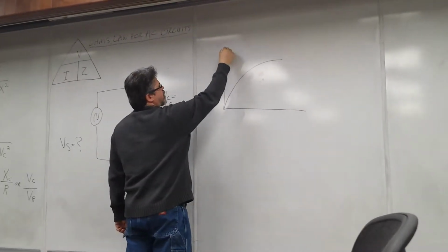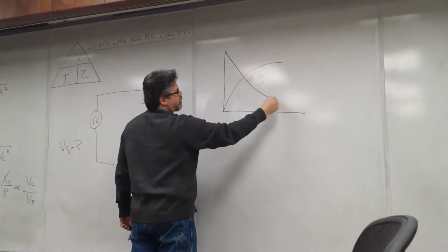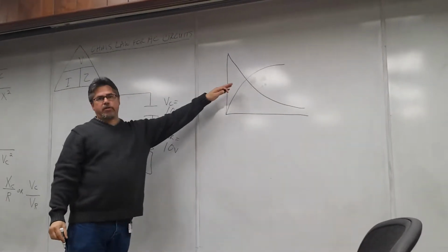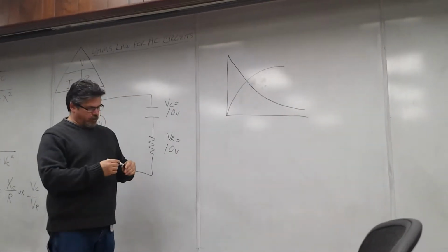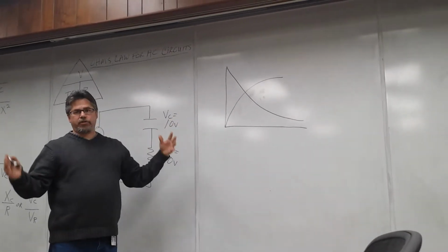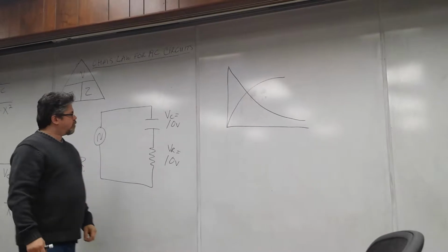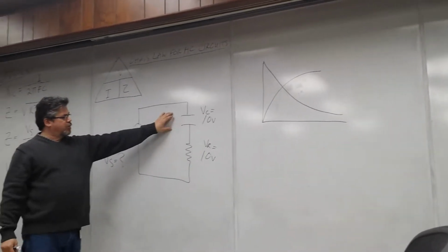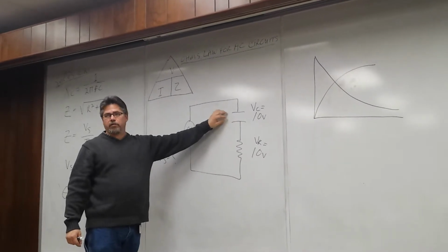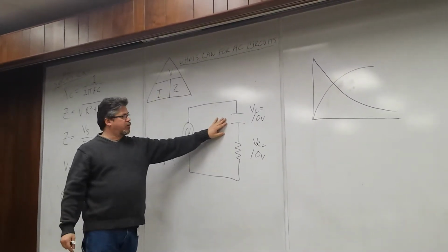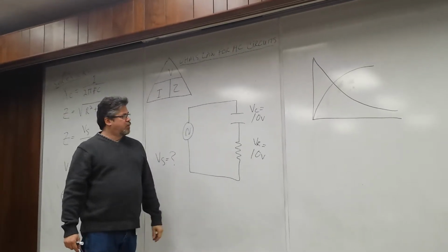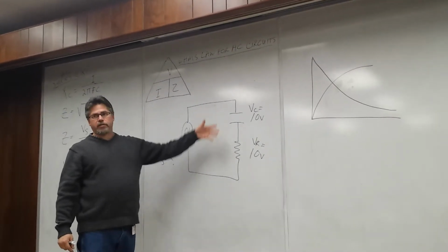Meanwhile, the current starts out as max and it dips down exponentially. But because of this time constant, because of this opposition to the flow of voltage, it displaces voltage and current throughout the circuit. But across the capacitor, that displacement, no matter what value the resistor is, or the capacitance value, microfarads or picofarads, you still have a 90-degree displacement between voltage and current. If you put a scope across it, that's exactly what you would see.